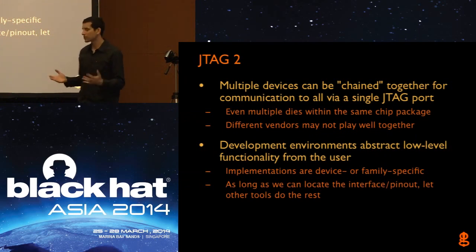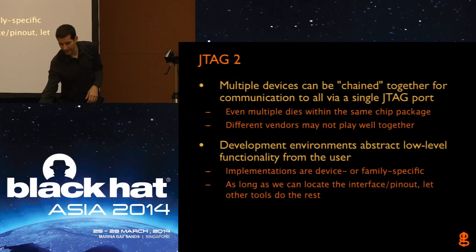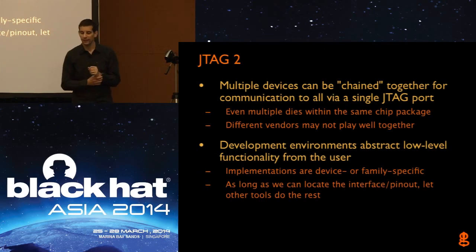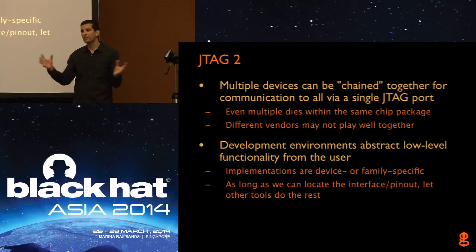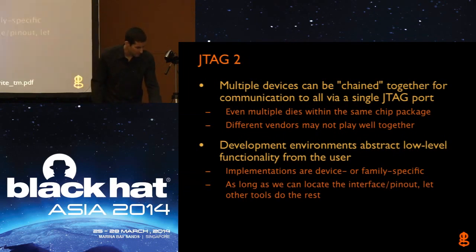Usually what I tell people is try to put yourself in the mindset of the legitimate engineer that designed the product. So say we're looking at an access point with a Broadcom BCM4702. I would try to find out if there's a development environment for the 4702, and is there a recommended JTAG hardware to use for that architecture? I believe that was an ARM-based architecture, so I'd probably find something that supports ARM. Because then everything's abstracted, and we don't have to worry about low-level stuff anymore. So that makes it nice.